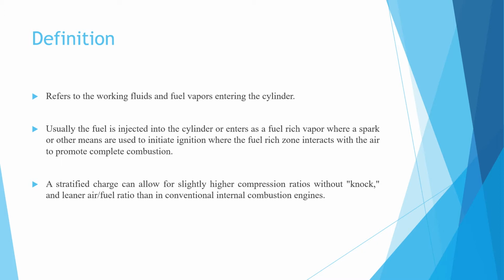In case of diesel engine, it has good part load characteristics, but it has low smoke limit, limited power and higher weight to power ratio. The use of higher compression ratio poses an additional problem of maintenance and higher losses in a diesel operation.